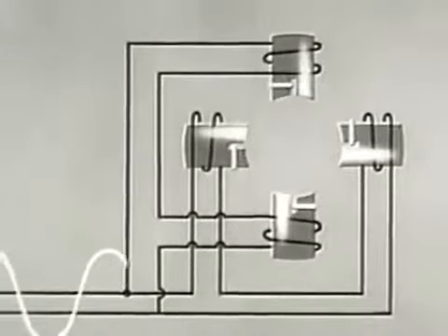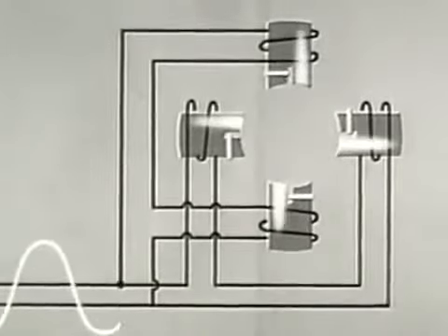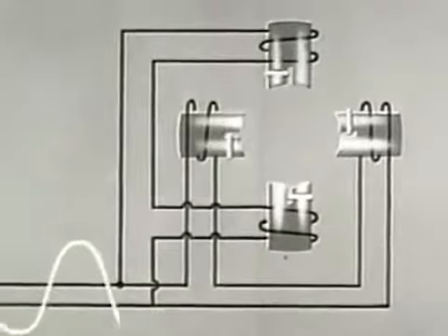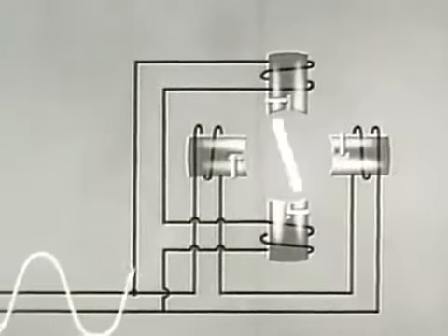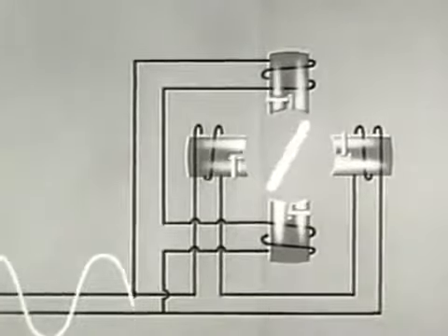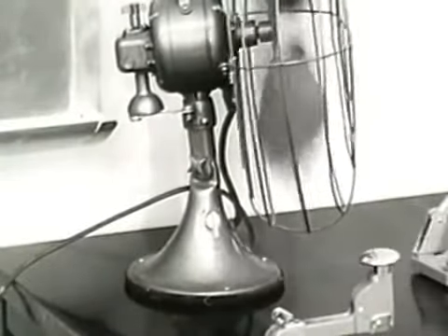As the current cycle changes, the same action will take place in all the poles. Relative motion, the basic requirement of an induction motor, has been satisfied. The rotor turns. Because of the relatively small phase difference developed by this method, shaded pole motors start slowly and are not used where a great deal of starting torque is required.